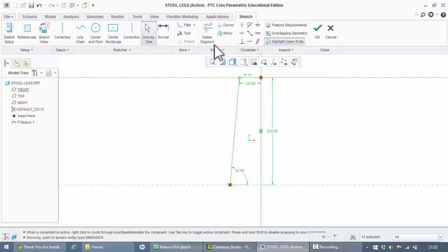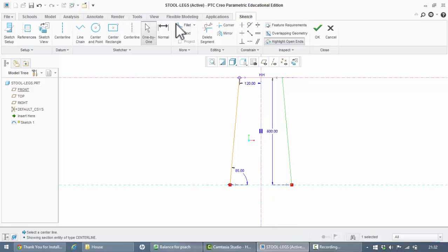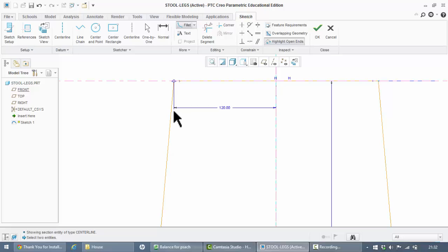Creo knows we've got some lines selected, and the mirror command's available now, and we can click on this line here and it's mirrored everything around that. It would have been nice, actually, thinking about it, if we just zoom in on this area to put a fillet, which is a curve, between those two lines. Notice it's not repeated on that side,